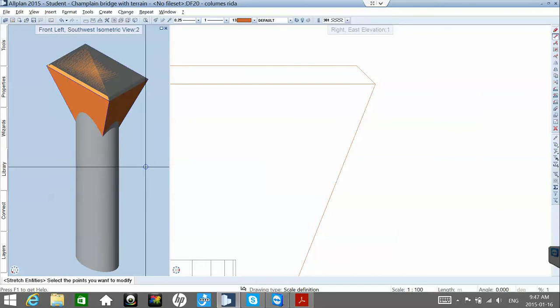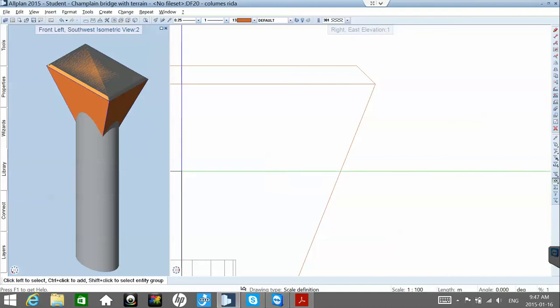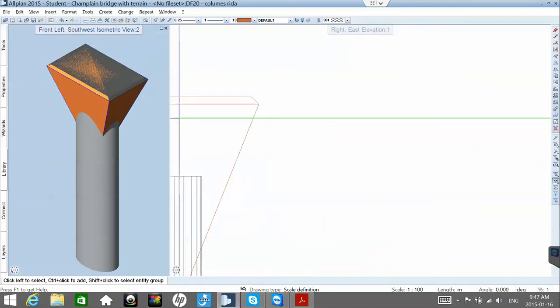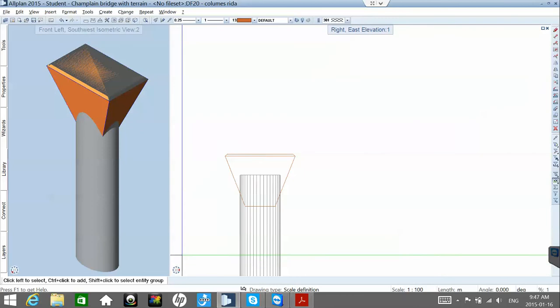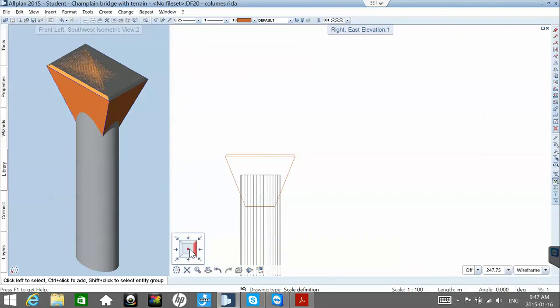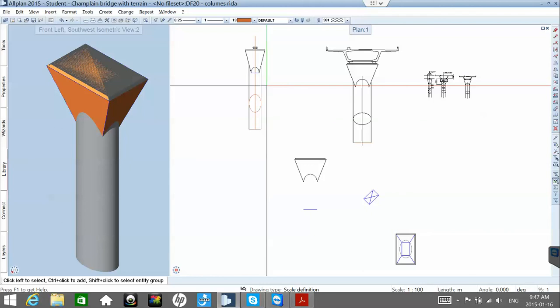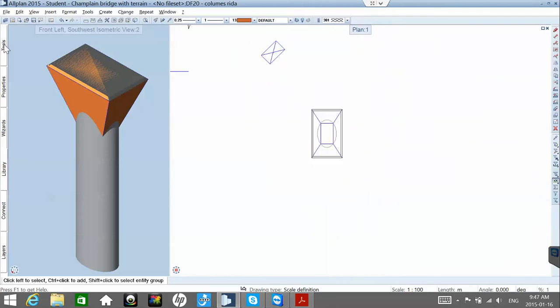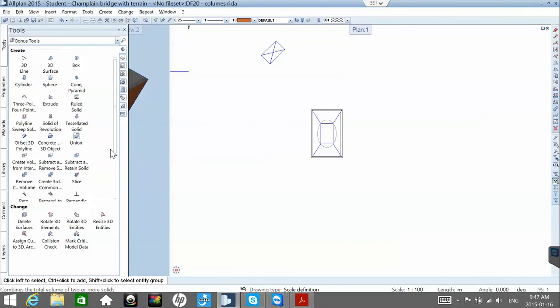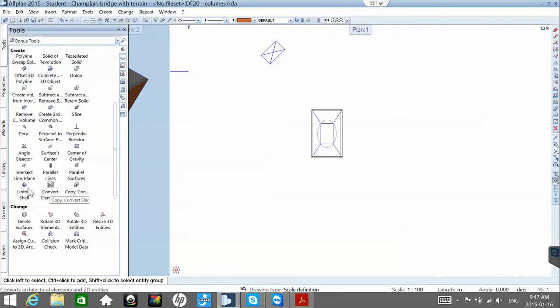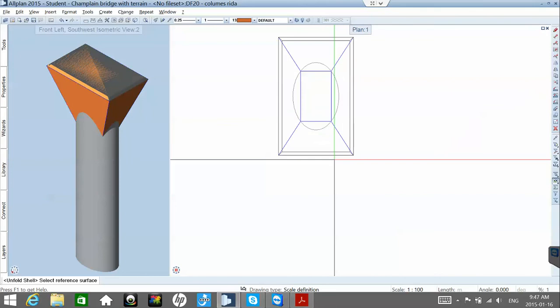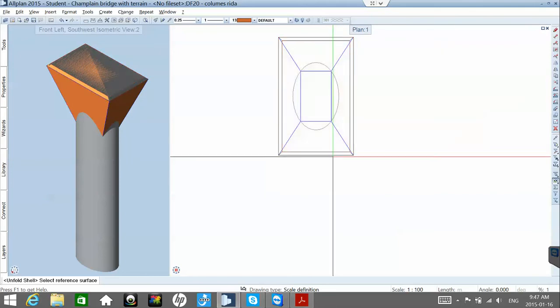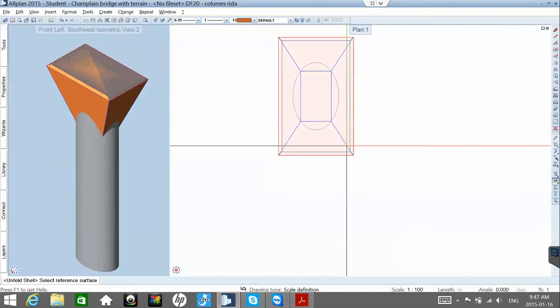And now you can also get quantities and volumes from it. So that's why we need it to be a 3D volume. You can also get something really interesting now to make things worth your effort. You can actually do an envelope of it. So let me show you something interesting. If you would like to know the formwork of this shape, you could go like this, unfold shell, and this would be the shape we are unfolding.